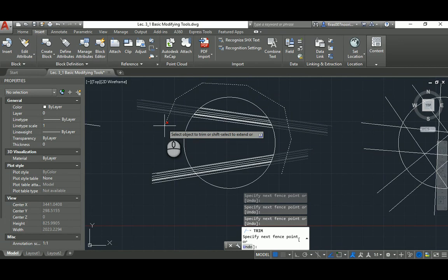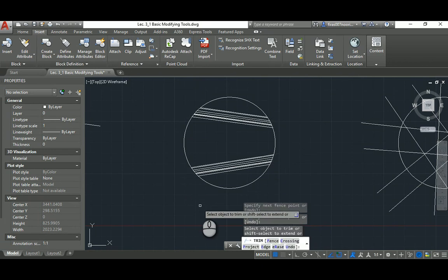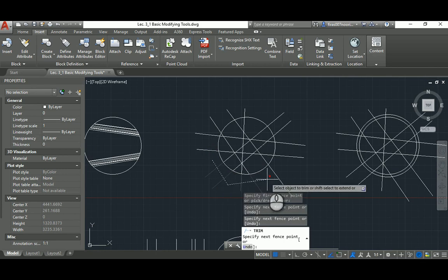If you have many lines, like 100 in each case, you might notice that AutoCAD needs some extra time to do this. If you cut without seeing it go gray, some of them might not be cut. That's a fast way to do that. Again, F space.